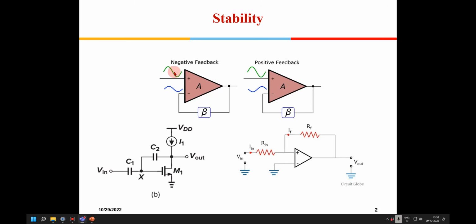In negative feedback, the condition is that these two signals should subtract from each other. Here, because of certain elements in the beta network, the signal is inverted by 180 degrees. So now if you try to subtract these two, they get added up. We essentially land up in a situation where this system is not stable.